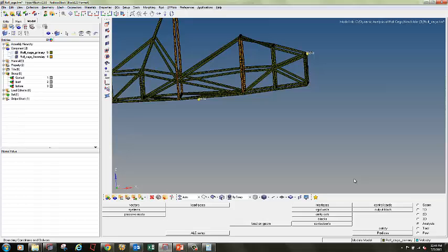So now the next step, the last step before solving the Radioss dynamic analysis of the crash analysis of the roll cage, is to define the control cards. For the engine file, in dynamic analysis it creates two files, the run and the engine. To define the engine file, we have to define four important cards. If you don't define those cards, your animation will not run, or your model will not solve. So the four cards which you have to define properly are as follows. First, click on analysis control cards, go to next.